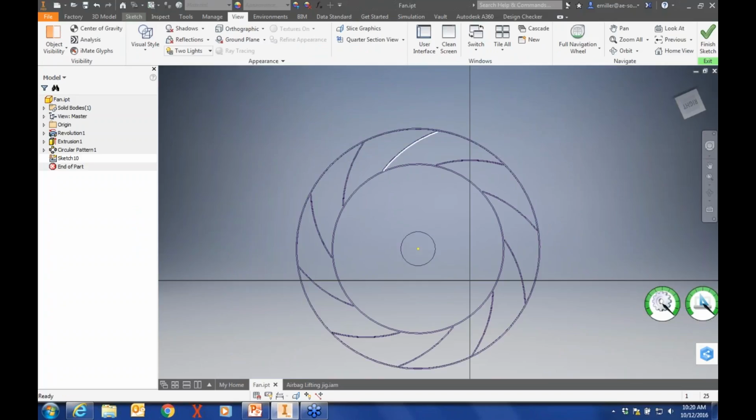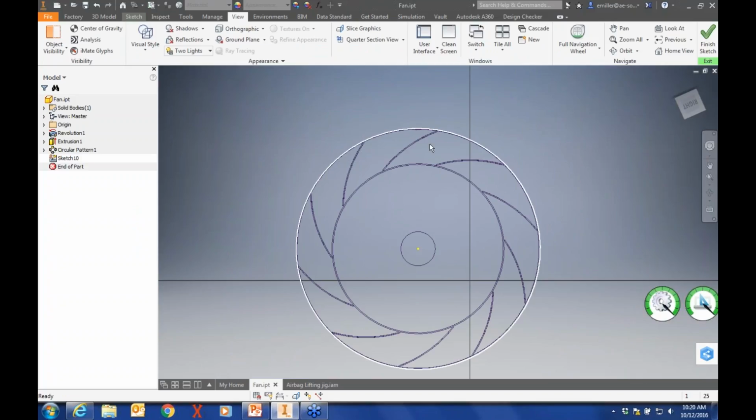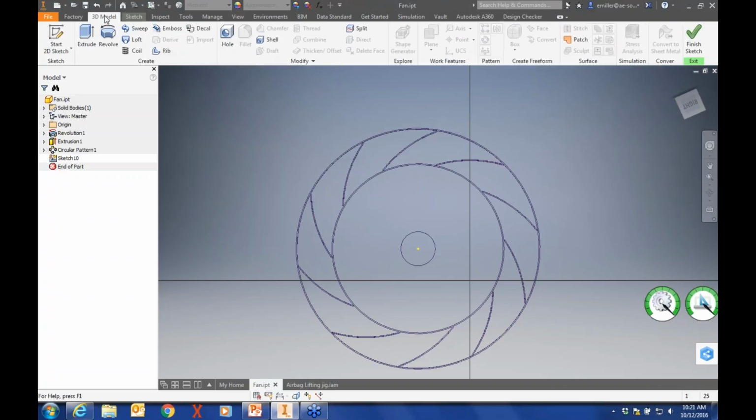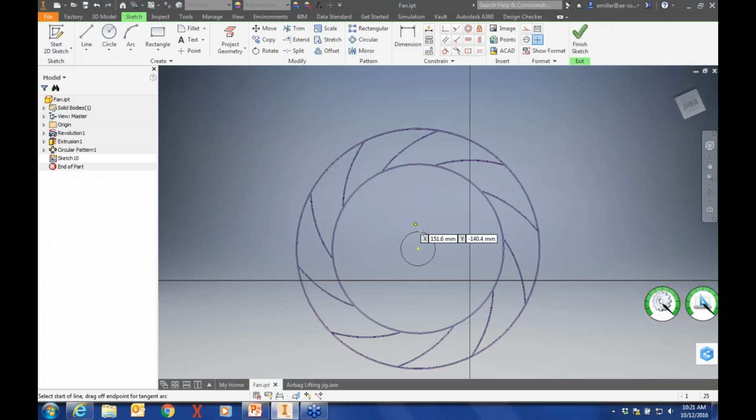All right, and actually, what if I don't want to rotate that? Well, let's go ahead and create it the initial way we were talking here. I think if I cut it, you wouldn't have to just go straight up. Obviously that would cut this fin. Maybe I'll go up and then kind of angle over with this cut. All right, so we're in our sketch environment still here. Let's go to the sketch. We'll just start a line. We'll start at the center here, go up a certain amount, and then I'm just going to come over to kind of cut that piece off.